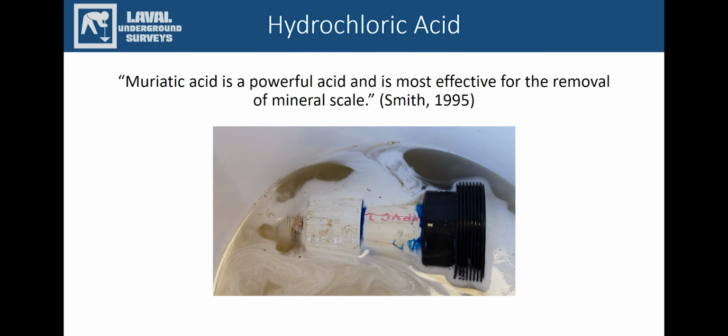The resulting bubbles are from the acid interacting with the mineral, which produces carbon dioxide. This is a good reason to try doing a bucket test to tell whether this is a mineral scaling problem or something else. This low cost-effective pre-treatment option will help you save time and money in the long run.